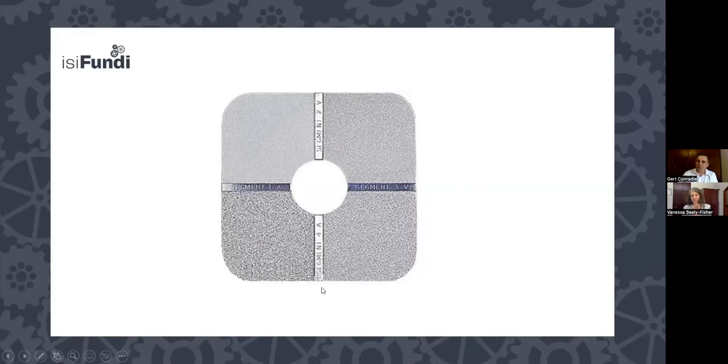This being a visual comparator, you can now, in this instance, use a magnifying glass, look at your surface, look at this comparator and say, does it conform to these 2 segments at the top, which will be a representation of something that's recorded as a fine measurement, or is it more within the next range, which is the next 2 down the side, which is then referred to as a medium profile, or is it across the bottom of the actual comparator, which will then refer to it as a coarse profile.